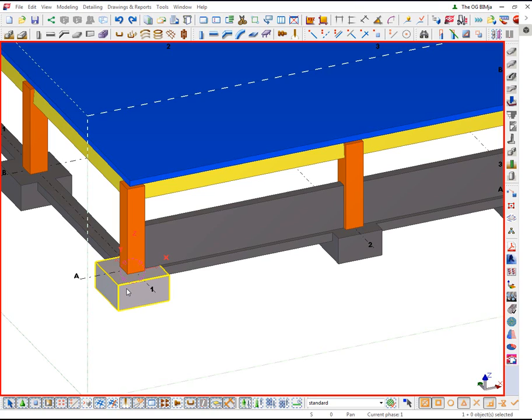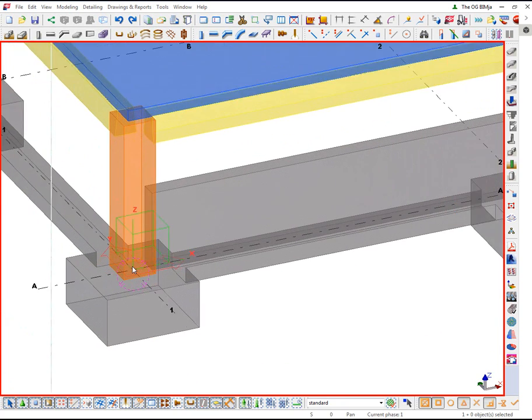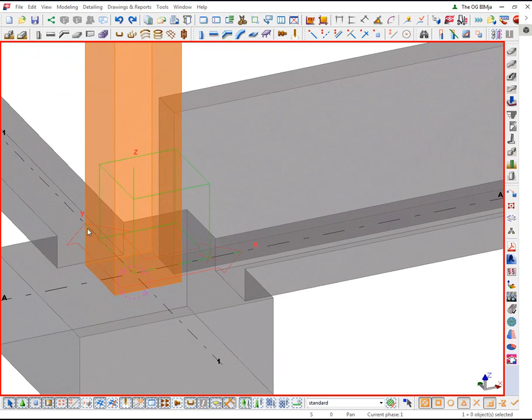So what we can do is we can change the work plane, and that is what Tekla is going to use for my IFC export. So we're not actually moving the model, we're moving and changing the origin. So the origin that the IFC export uses is this work plane, so this red XY that we see right here. Not the red Z, Y, X. That's the Tekla global X, Y, and Z, so we can change this.